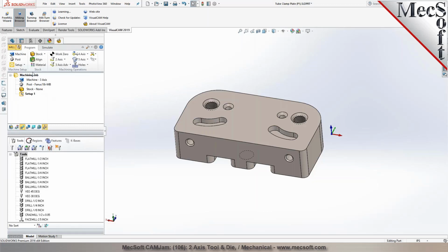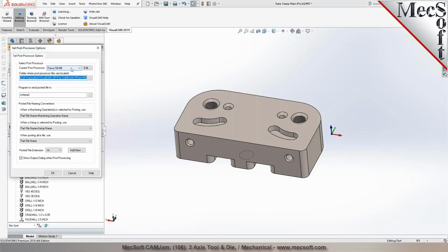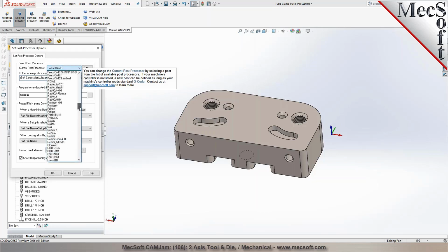In the next step, we want to pick the post processor. This would be the machine tool that you'd like to output the code for. Do you happen to have the information for that? It's the FANUC 21. Okay, so we currently have several different posts for FANUC here. We have one for 21i, 21M. We have different variations of the FANUC post in here, and we can always customize each of these posts to output the code that's similar to what your machine is expecting. So I'll go ahead and pick the 21M. Would that be okay for the demonstration?